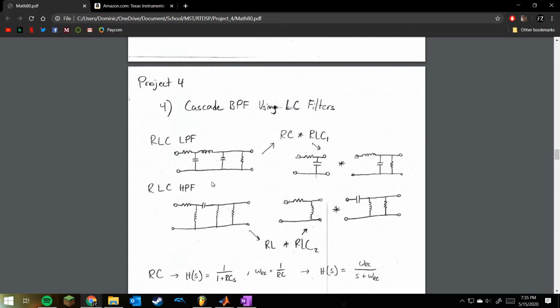The resistor on the end here is to help with the impulse invariance derivation of the transfer function, or the z domain transfer function. That is, it allows us to sort of complete the square in the denominator, and we'll see that happen there. And you'll also see it happen with this one here as well. And then same story for these resistors on the high pass filter.